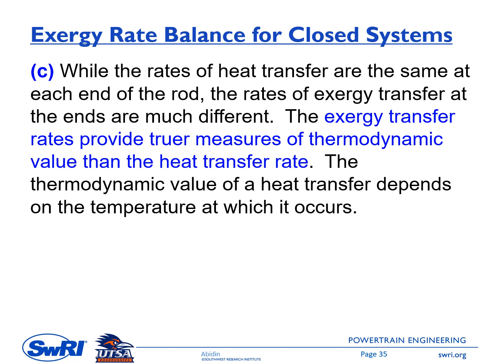But you can see that the rate of exergy transfer at the ends are much different, right? On the left side, we have 50 kilowatt. On the right side, we only have 3 kilowatts. So 47 exergy are lost inside the rod. So the exergy transfer rate here provides truer measures of thermodynamic value than the heat transfer rate. The thermodynamic value of the heat transfer depends on the temperature at which it occurs.